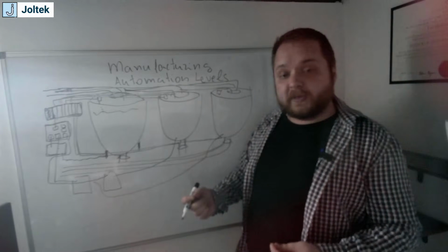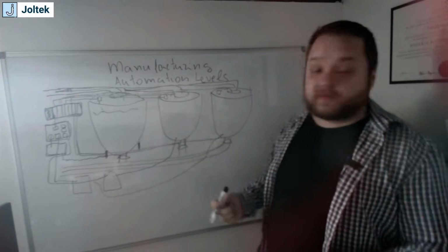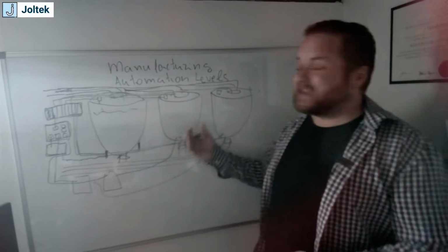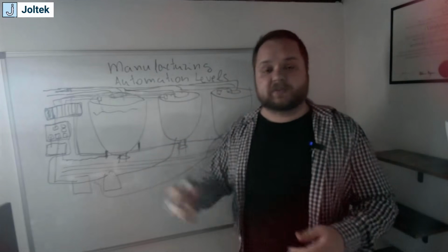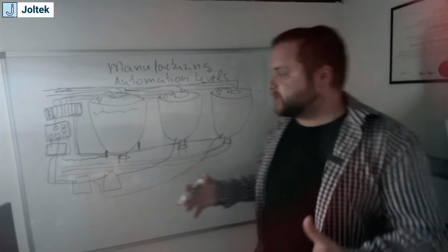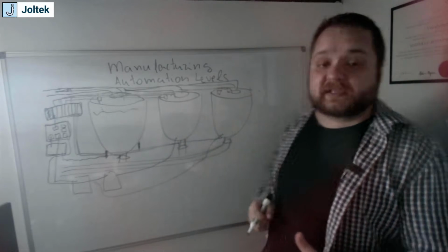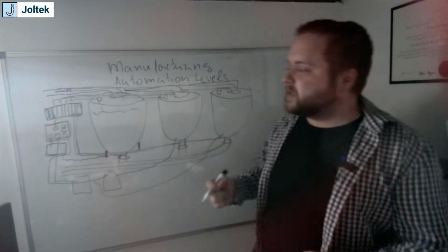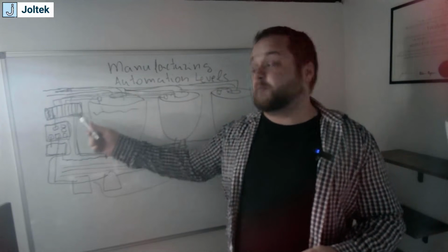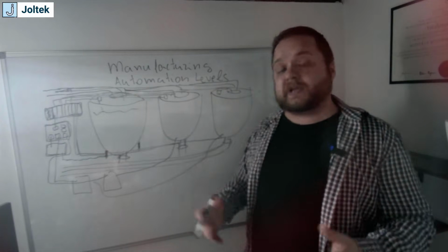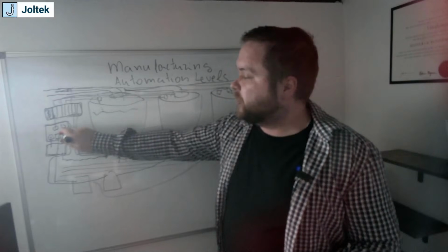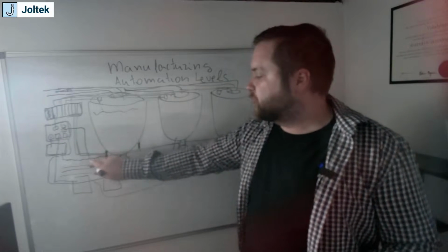So for example, imagine for a moment that you have this specific tank farm, and now you're looking to add a second replica of the same tank farm, maybe at a facility that's going to be right outside of the current one, right? So you've built a second facility on the process side, and now you have a replica of this exact same control system. Does that necessarily mean that you need to purchase all the same PLC peripherals and components? And the short answer to that question is no, right? Because you can use what's called a remote IO. So here from the switch, I'm going to draw a cable, right?